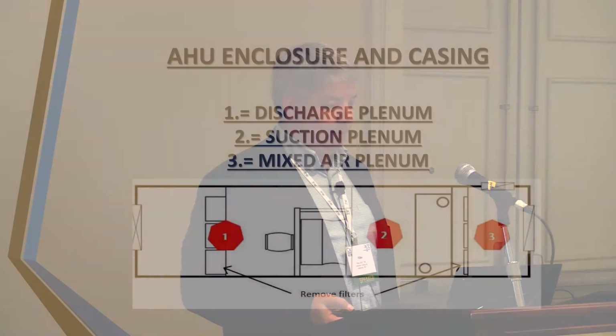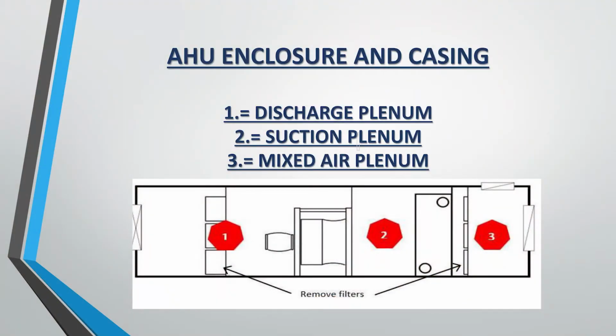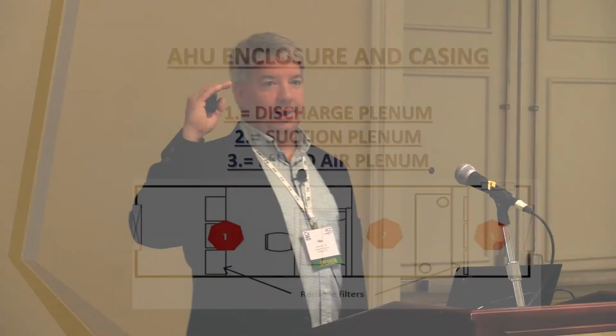Basically what they're saying. So when we got to this unit right here, it became a contention point. They wanted to go by, hey, we got this perfect report that said this unit was leakage tested at the factory. University of Maryland and their people wanted it that way out here in the field, and it became rough. So what they ended up deciding on this specific project was they wanted to test it at 6 inches. Well, the unit was never going to operate at 6 inches of static. Just never going to be there. It's going to operate somewhere in the 2.5 to 3.